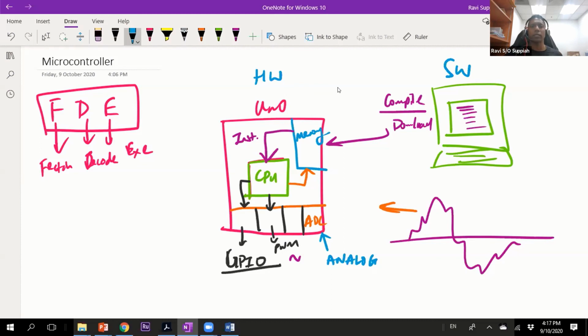Hardware-wise, again, you need to build some components, some filters, some light sensors and so on, and then connect them to the MBot pinout. So the MBot doesn't look like Arduino, but it is still based on the Arduino. So it's the same sketch programming language that you're going to use. The good part is, like I said, since some of it is already pre-built, they have readily available software libraries that you can use to control all these subsystems.